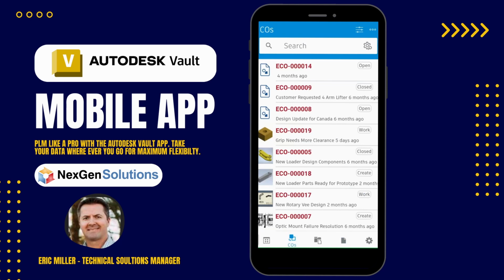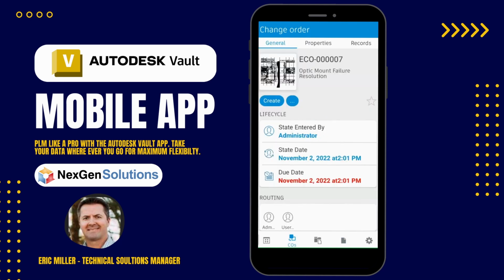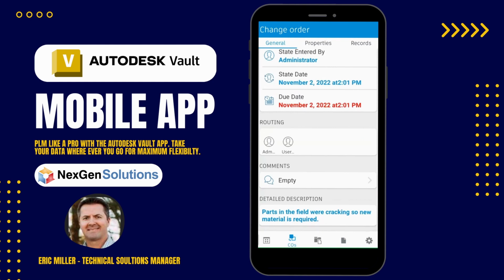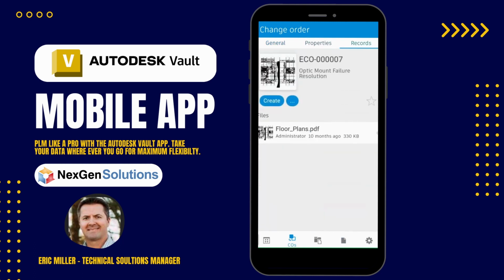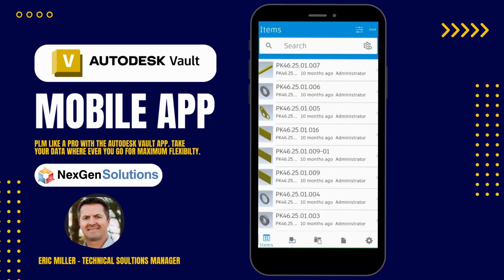I'll give one more chance here to take a look at an ECO. Yeah, okay, so we're going into an ECO. We can go down and see the routing. So currently you can see the people that are involved in the routing, the comments in here, look at the properties, different records that are associated with this. So this is just a PDF associated with this one currently, but we could download that, look at that one here too. And right now it's at the create state, so if I wanted to submit it or if I wanted to sign off on it, approve it, things like that, I'd be able to.